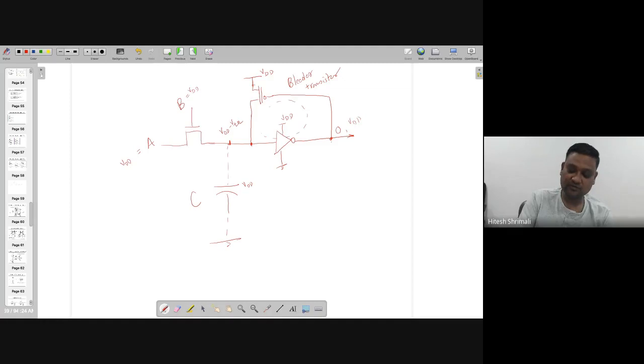and because of the propagation delay in this loop, along with this capacitor, I am going to have VDD over here after some time, determined by the PMOS transistor multiplied by this capacitor. So let's assume that this node capacitor is the biggest one, right? And it's a combination of the capacitor by this one, the capacitor by drain to body.